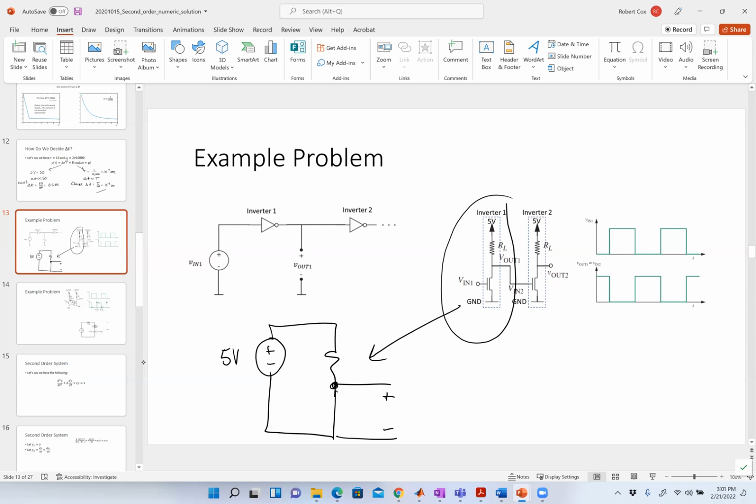So basically, putting a voltage here controls whether I get a 1 or a 0 out. If I put 5 volts at this input, this switch turns on, so I put 5 volts in, I get 0 volts out. If I put 0 volts on this input, then the switch turns off and I get an open circuit. What's the voltage going to be then?